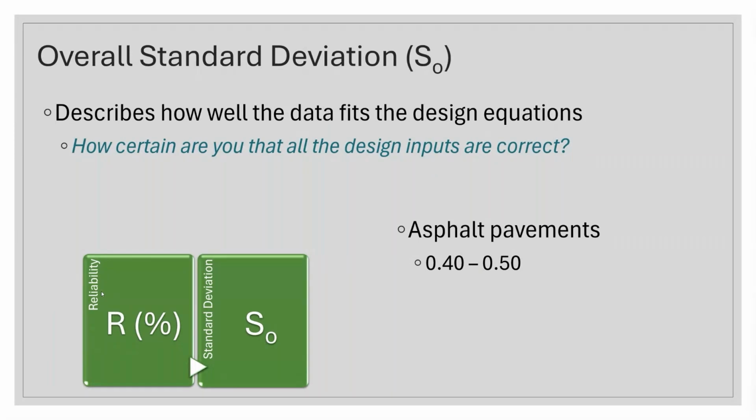And then overall standard deviation. This describes how well the data fits the design equations. And we know that those equations were developed for one location with a set of materials that may or may not match the rest of the country. So we're saying, how certain are you that all of your design inputs are correct? And that goes beyond just the traffic and that kind of thing.